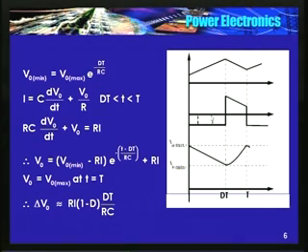It's because I assume that the capacitor is charging for the entire duration when the switch is open. It is discharging and then charging here. At this point, the switch is closed again and the inductor current starts increasing.